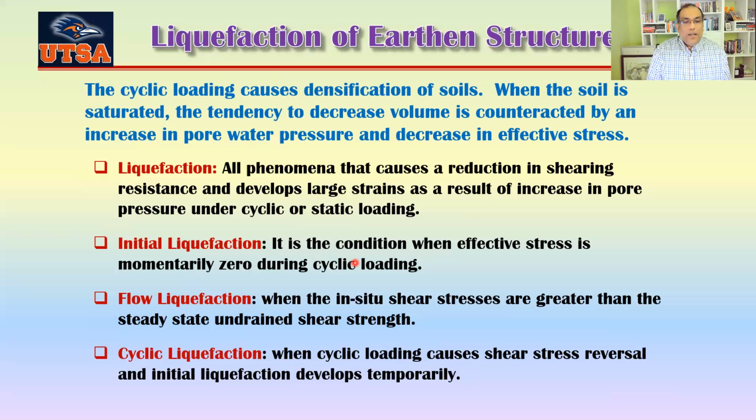Flow liquefaction is when the in situ shear stress is greater than the steady state undrained shear strength. Okay. The in situ shear stress is basically higher than the strength, then basically this will start flowing. That's flow liquefaction.